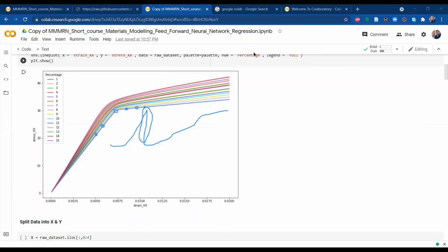If you're working with polygon structure, you can think of grain size or grain diameter as one input variable, and maybe, what else, if your work depends on the temperature, you can think of that. And also for stochastic, you can change the size of your RVE that you are considering for modeling your grain structure. So those are the things you can vary and see the effect. Output can be stress and response or whatever you want. I'm not sure if it answered your question completely.